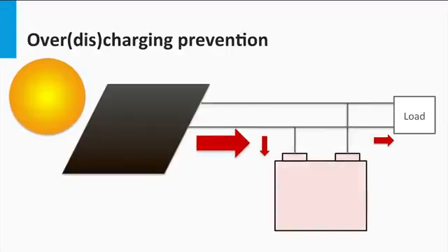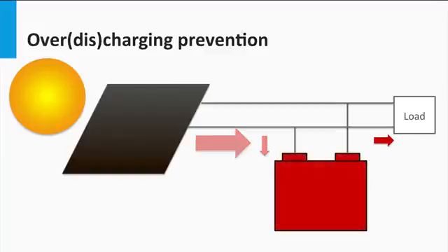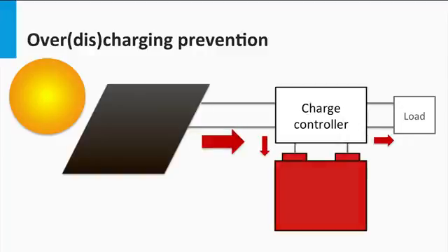When the sun is shining in peak summer, there is enough PV energy meeting the load. The excess energy is sent to the battery. But when the battery is fully charged and the PV array is still connected, the battery tends to overcharge. This brings about its own set of problems like gas formation in the lead-acid battery, capacity loss, and overheating, to name a few.